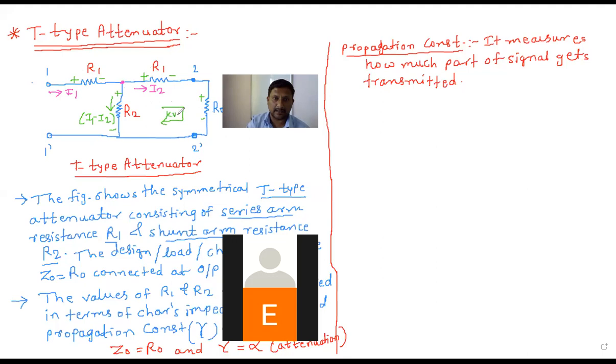Apply the KVL here. So write, apply KVL, Kirchhoff's voltage law, in the loop which is marked here. You can start from any point. While applying KVL, we are selecting the left hand side bottom point as the first point as well as the last point. So go in a clockwise direction. The polarity and current are already marked, and the value of resistance you know. So we can start here.